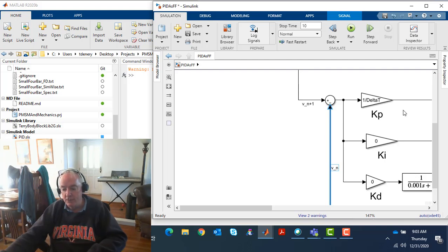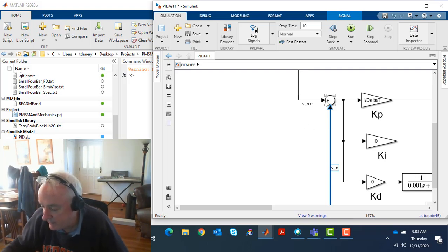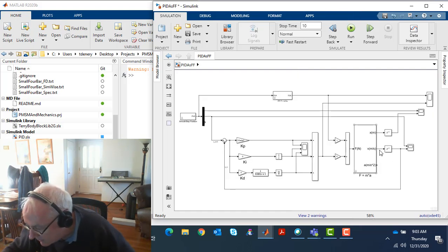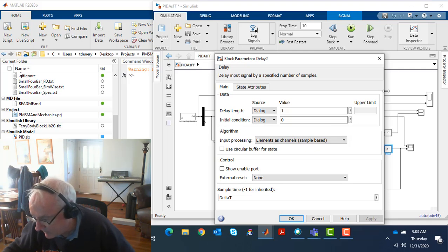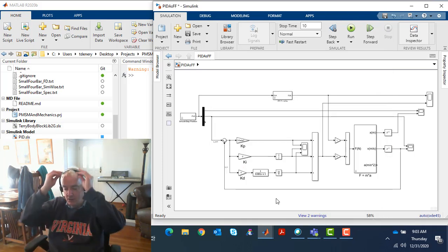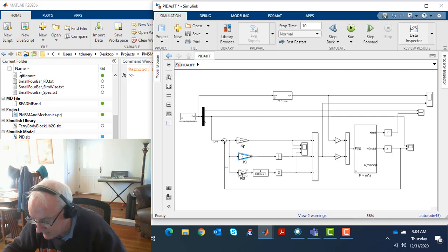And what I mean by doing right is that we're applying the appropriate force on the system, and therefore, by the very nature of it being a mass subject to the force that we're going to apply based on this calculation, we're going to be real close to v n plus one for our next time step, right? But anyways, this difference, v n plus one minus v n, and then my kp, my proportional gain, I make it equal to 1 over delta t, right? And I'll just show that in my capture of the velocity signal to be consistent with all of this, you'll see that I am discretely assessing it and that my sample time is delta t. So I think that's a pretty reasonable explanation of how I did this, and you'll certainly see that ki and kd are both equal to 0.